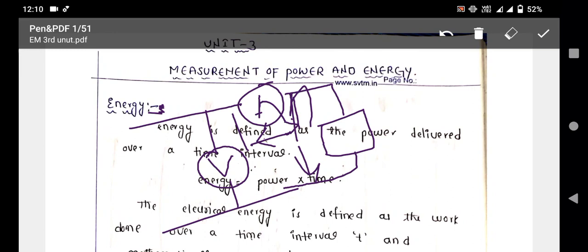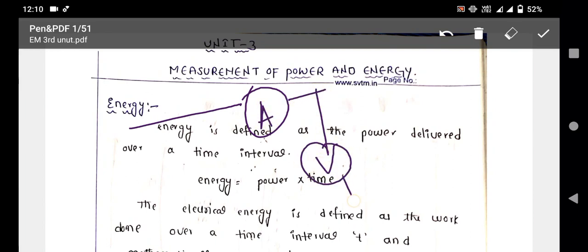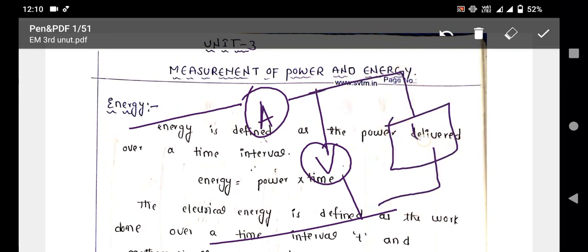Assume the load is resistive or inductive or whatever. The ammeter carries the load current IL and also the voltmeter current. So the ammeter not only reads the load current, but also the voltmeter current.